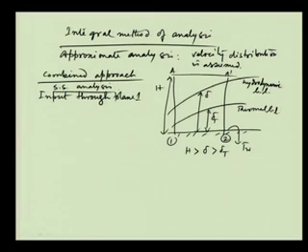So, input through plane 1, that means from this left face. Now, how much mass is entering? It will be the integral from 0 to h of rho V x into dy, correct. And rho into V x into dy into 1, we have already discussed in the last lecture. This is the area: rho V x into dy into 1.